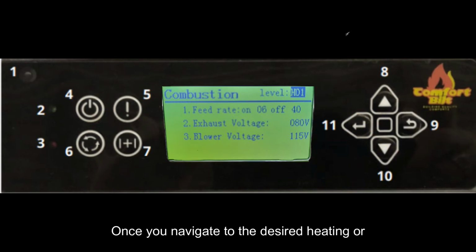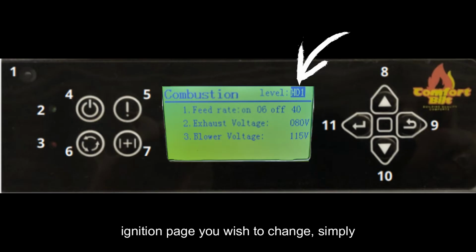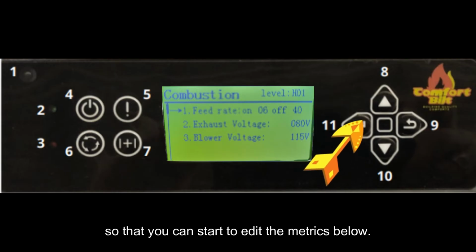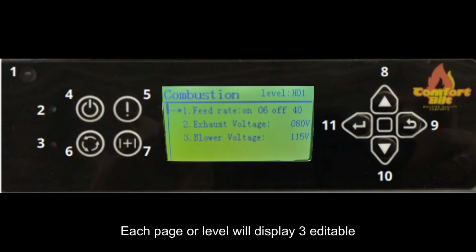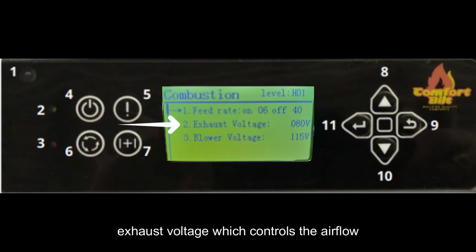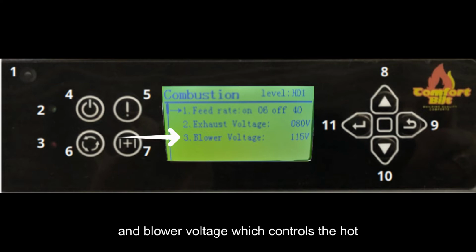Once you navigate to the desired heating or ignition page you wish to change, simply press the Enter button to lock in the page so that you can start to edit the metrics below. Each page or level will display 3 editable metrics: feed rate, which controls the pellet delivery; exhaust voltage, which controls the airflow or air pressure for combustion; and blower voltage, which controls the hot air distribution into the room.